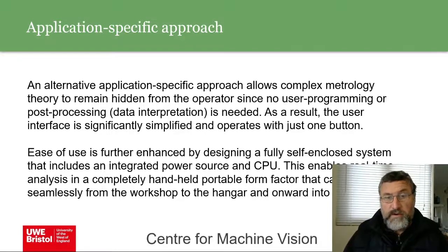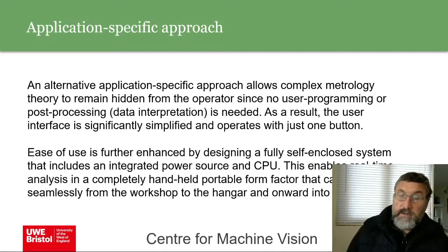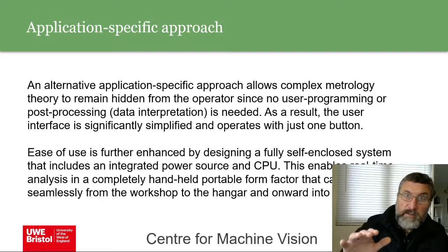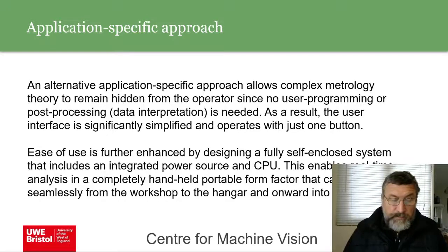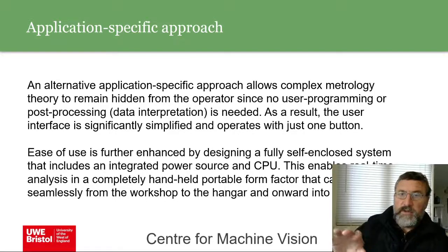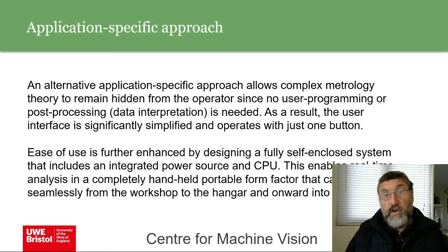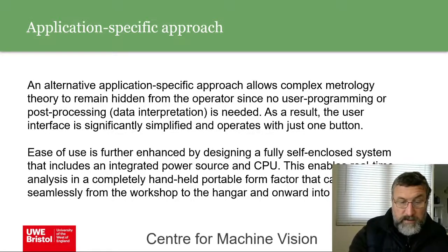If you notice some damage at a certain point, you could continue monitoring it and seeing whether it's getting worse, whether it's moving up the control chart. A control chart has the time on the x-axis and size of the defect on the y-axis, and then control limits to where acceptable damage limits are. And you can even do a thing called a CUSUM chart, where you accumulate the damage, and it's very good at showing you trends that are occurring in measurements. So that's a whole area of statistical process control. It's one I've got some experience in. It's quite interesting because if you're getting this data, then you want to make use of it in the best way you can, really, through statistics, for example.